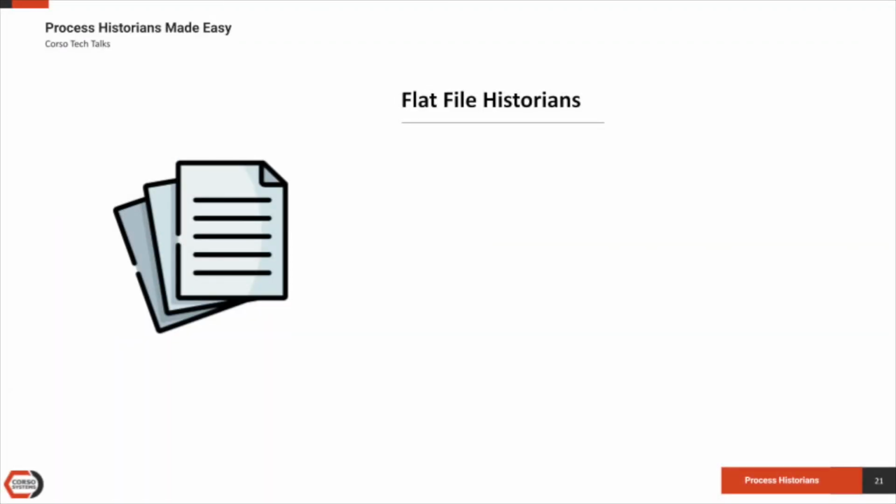Flat files, on the other hand, are purpose-built for whatever historian is using them, so they can be highly optimized and compressed, allowing you to dump a lot of data very quickly into them, and given their optimizations, reading data from them can be very fast as well. The downside is you will likely need to build an API to make the data accessible if you're the historian developer, and if you're using the historian, you'll need to use an API to interact with the data instead of a database query.